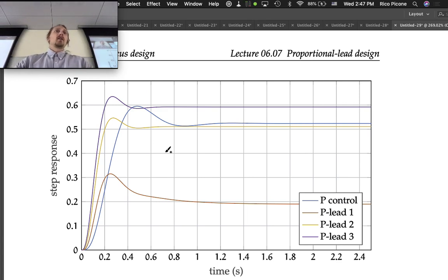transient response issue, which is to say that we wanted it to be down around 0.4 seconds for the settling time and 10% overshoot, whereas we're definitely over that for our settling time in the P control, and it looks like it also overshoots too big. So we hopefully fixed that. We have these three different cases. So in all three cases, it looks like our settling times improved.